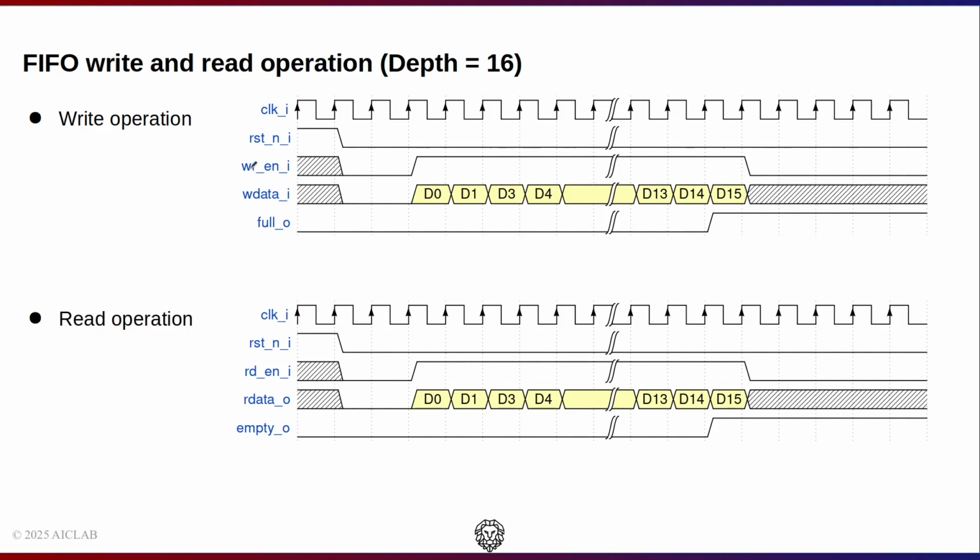and then set the write enable. The writer can continuously write to the FIFO. During the last write, the full flag is set to 1. It tells the writer module that this is the last write operation, and after that the FIFO ignores the write operation.